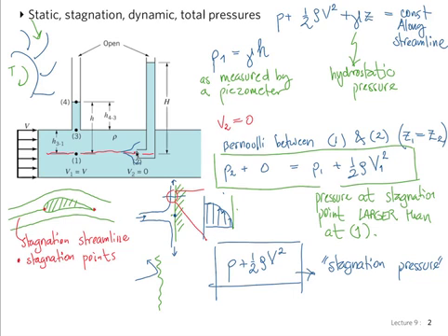But we're looking at the places where we know things. At 1, we know the velocity is the unperturbed velocity and the pressure is the static pressure there. From 1 to 2, we can apply Bernoulli's equation, where the only unknown at 2 is the pressure. We can interpret this as the kinetic energy and the pressure having all been turned to pressure at 2.